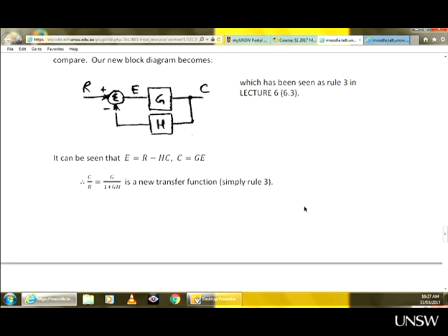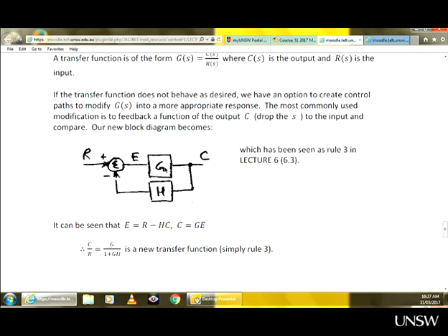When you have a system and it's running for a long period of time, there will be changes. So some of the parameters will change. I mentioned that spring mass damper system. If it is working outdoors, you may have some corrosion, so the mass will increase. Or you may have some physical damage, so the mass will decrease. That spring, that keeps being extended and compressed, after a while will change its stiffness. So that K is not necessarily constant. It is constant for a particular short period when you observe it, but over a few years, it is not going to be the same spring, the same characteristic. The damper, the oil might leak, not much of that, but enough to change C. So the system itself may deteriorate.